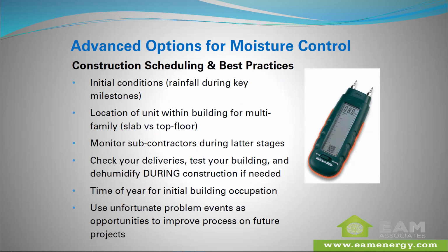The other thing that we spent a lot of time looking at was best practices during construction. We had a lot of projects that were having moisture issues in some buildings and not in others, in multi-building projects. We kind of brought that down to a case of climatic conditions during certain key milestones of the project.